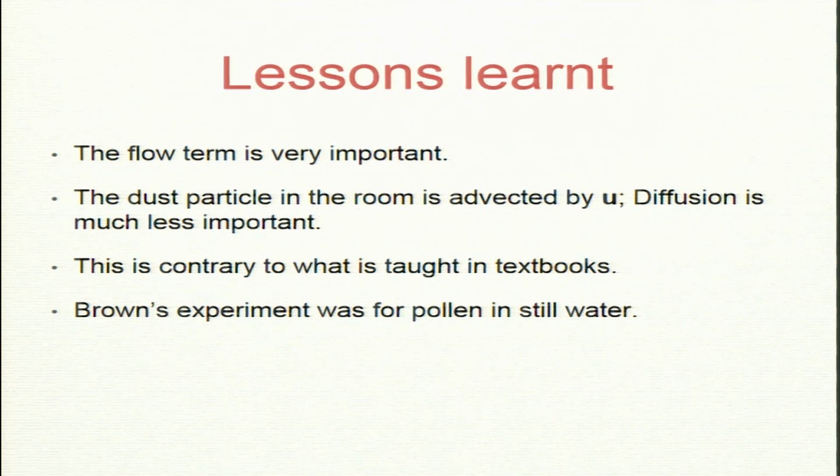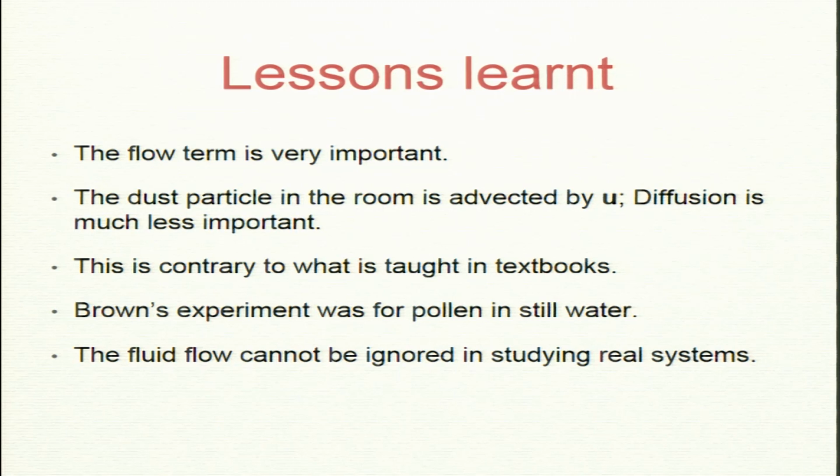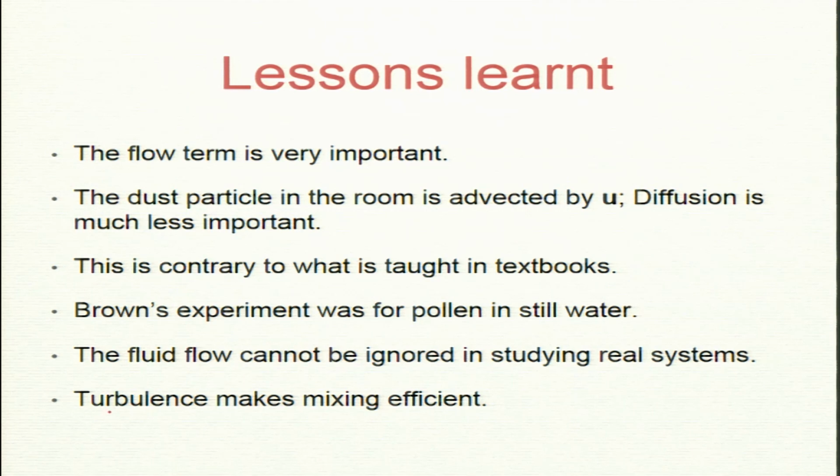So, the nonlinear term can be dropped; Brown did not need to worry about it. But in many experiments, real life scenarios, or even astrophysical scenarios, U dot grad theta is important, so it can't be ignored. And one important point, which we will discuss a bit later: mixing with the diffusion term kappa grad square theta was very slow, but what made it faster was the U dot grad theta term, and that in fact is turbulence.